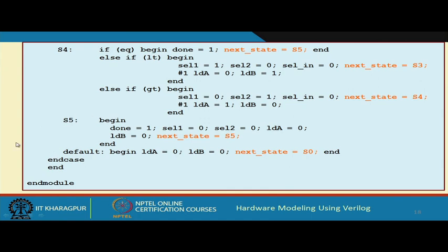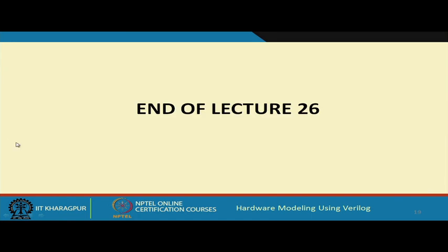Whenever state changes, you make some modifications there, generate the control signals and also assign the proper value to the next state, so that whenever the clock comes, the first always block will go to the correct next state, right. Fine. So, actually this is how this design is carried out.